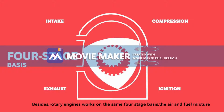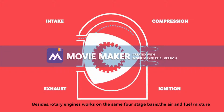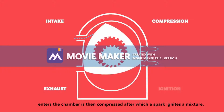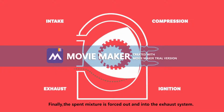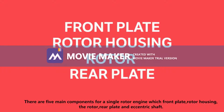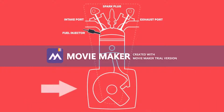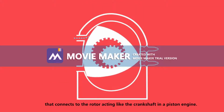Likewise, the rotary engine works on the same 4-stage basis. The air and fuel mixture enters the chamber and is then compressed, after which a spark ignites the mixture. Finally, the spent mixture is forced out into the exhaust system. There are 5 components in a single rotor engine: the front plate, rotor housing, the rotor, rear plate, and an eccentric shaft that connects to the rotor, acting like the crankshaft in a piston engine.